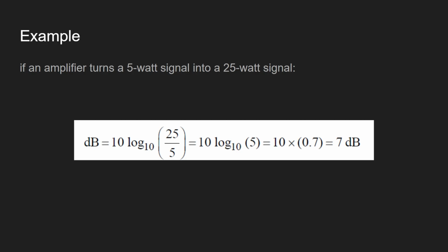If you have an input and output ratio like this, I'm trying to measure the signal strength, how strong the signal becomes, and we say it is 7 dB gain, which is 7 dB stronger than the original. So dB is just a comparison before and after, but not how much voltage you have to put in to amplify the signal.